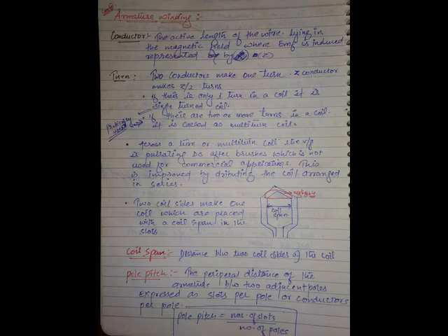If you extend this, if there are 6 poles in a machine, one complete mechanical rotation of 360 degrees mechanical will produce how many cycles? 1, 2, 3. So total 360, 360, 360, which is 1080 electrical degrees. Because how many poles? 6 poles.